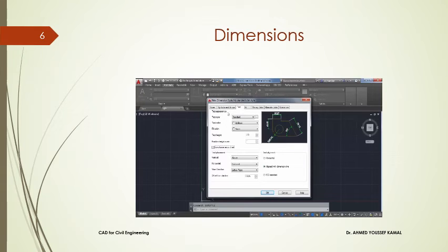In this text tab we have all the settings related to text, like text style. Let's change this text style. So right now we have a standard and annotative. We have not yet seen annotative, so I'll leave it for now, but we'll look at annotative property later on. If you want to change font style of your text, click on this small box.